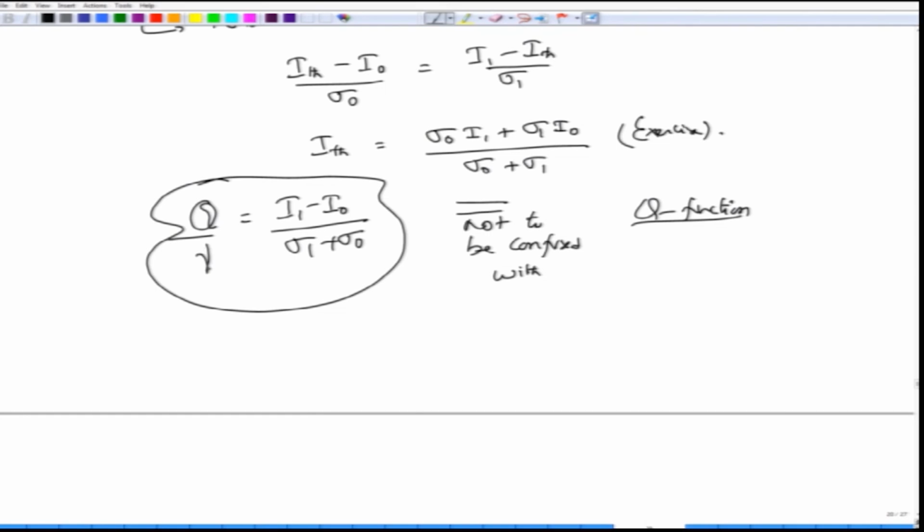So this value is the one that determines what would go into the probability of error, and this factor will be different for different receivers. For the pin receiver, suppose you want to obtain, let us say, a BER of 10 to the power minus 9.